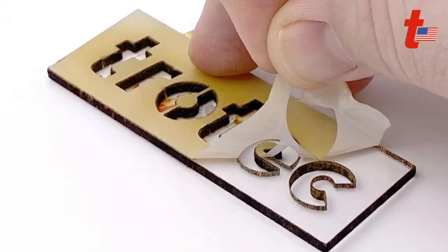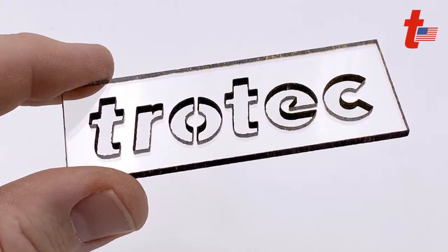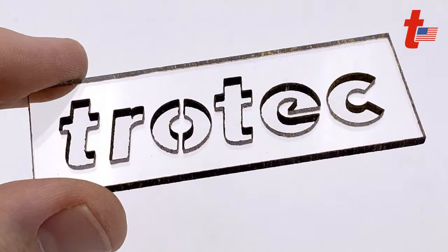Once you peel your film off, you can see the surface is beautiful, the quality and the edge is good, but you do get some distorted looking cuts, and it's just not a great material. Again, if the edges aren't going to be seen, and you're doing screw holes that are going to be covered up, this is still a viable application. But I just want to make sure that anyone attempting or running this type of material understands the main limitations for this material.